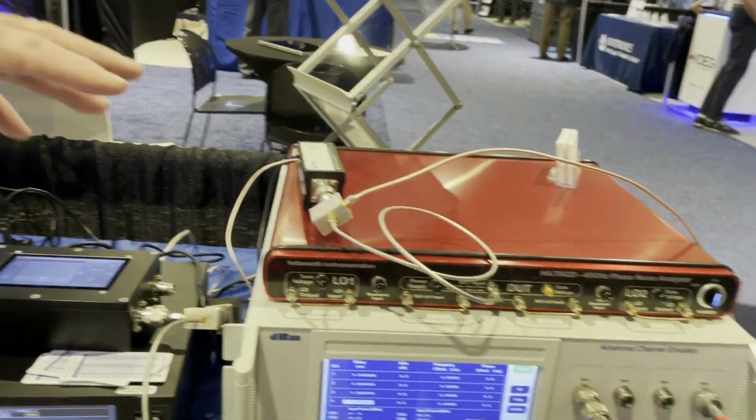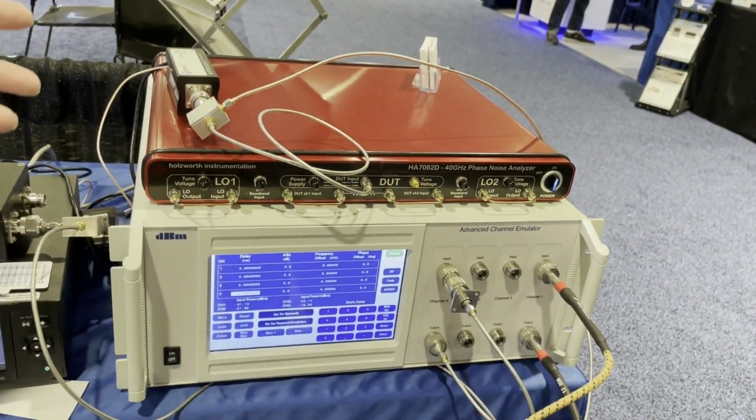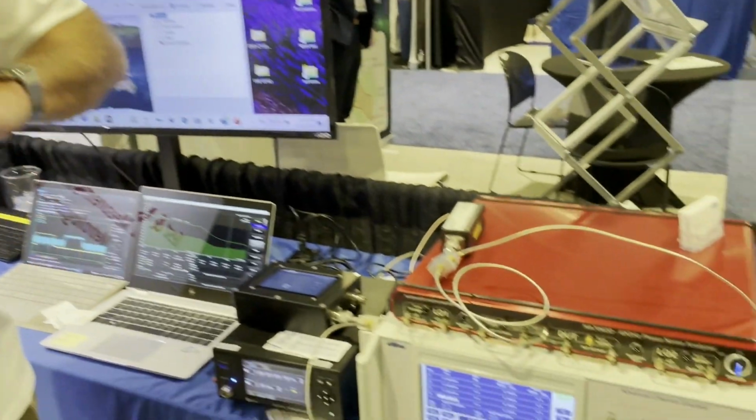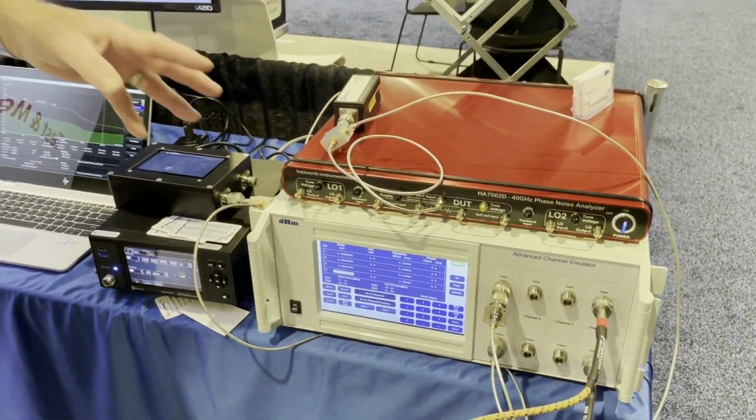So in addition to being able to emulate the RF link between uplinks and downlinks, we can also emulate hardware in the loop impairments. We can do things like amplifier compression, we can add phase noise, we can change the passband and ripple and shape of the transponder. This allows users to fully characterize their systems, either because the satellites are not visible or their signals are privileged.